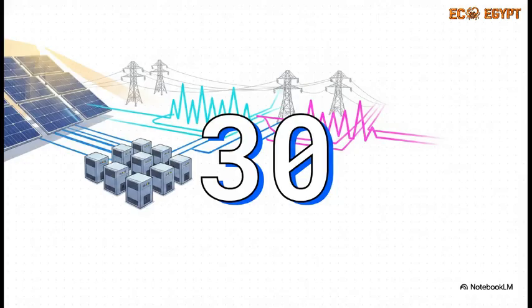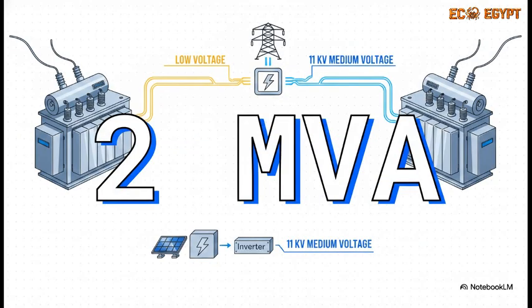And to handle that massive 4.1 megawatts of raw DC power pumping in from the sun, the Sphinx project uses a seriously formidable lineup. We're talking 30 individual Huawei 115 kVA inverters. These guys are the absolute workhorses of the plant, constantly syncing and converting that raw DC voltage into nice, usable, stable AC power. But here's the catch. We can't just pump that power straight into the utility grid as is.